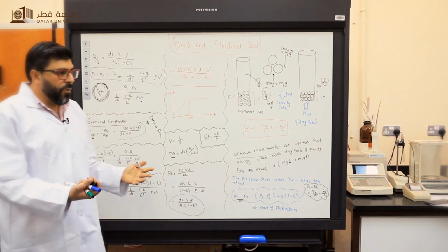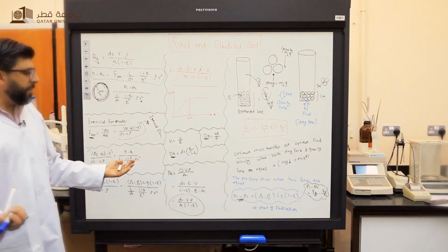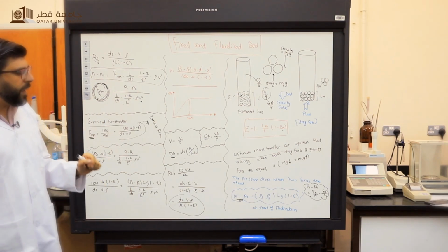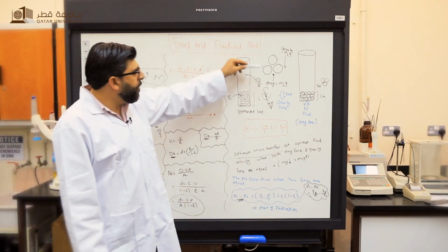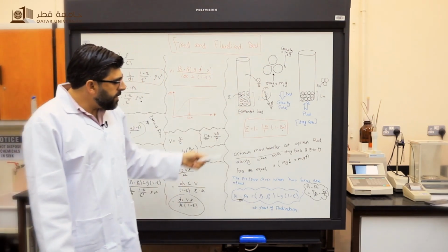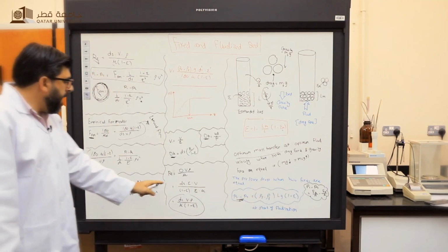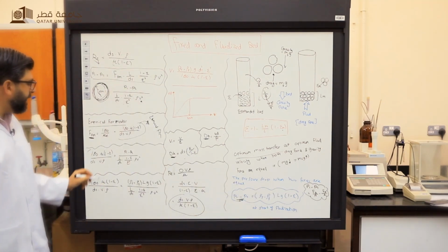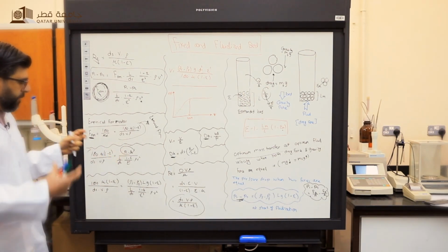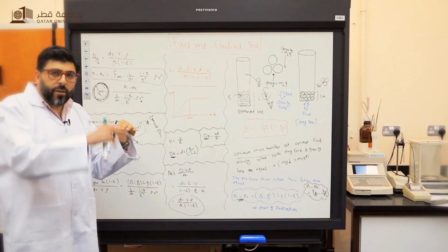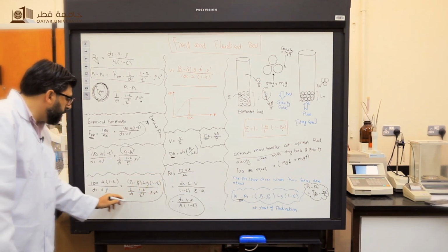Now, laminar flow covers a range of speeds, but my interest is to get only the speed at which two forces are equal. That means when the drag force is equal to the gravity force. This happens only when the pressure drop equals this equation, as we said before. So I will take this equation and replace it into here, to make the equation only for when the two forces are equal. So I just replace this one by this one, and this will be my equation.